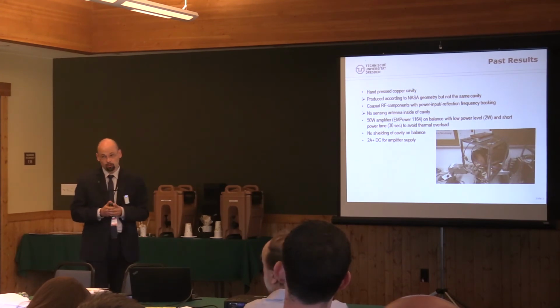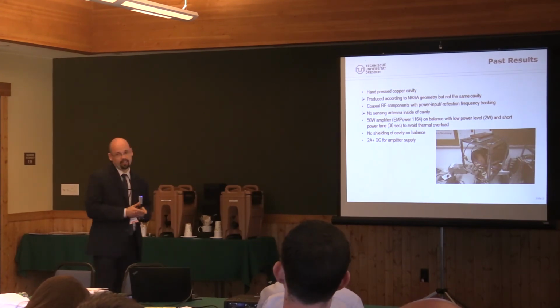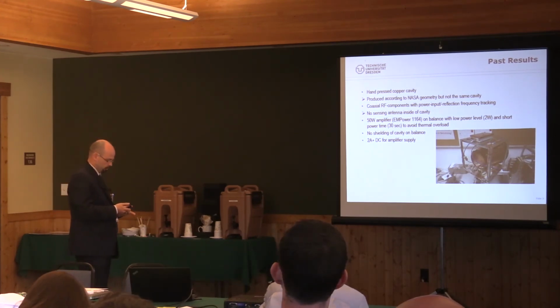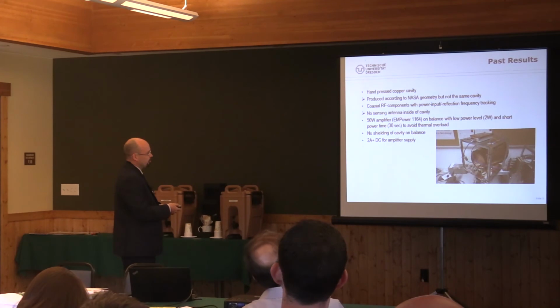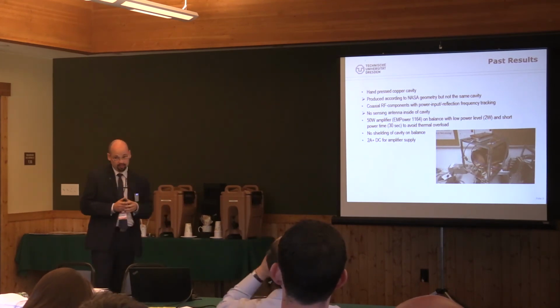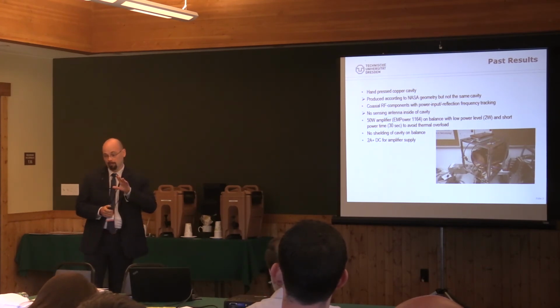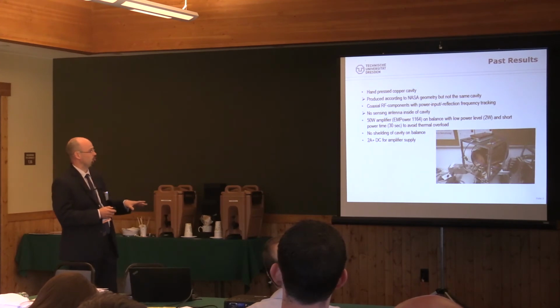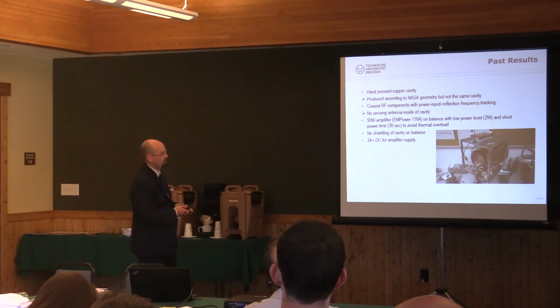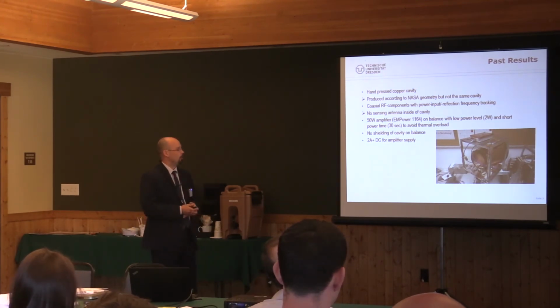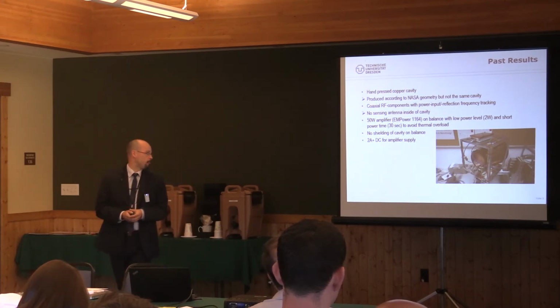We did not use a sensing antenna inside of the cavity in this configuration. We used the already mentioned 50 watts amplifier over the cavity itself, and this was also placed inside the vacuum chamber. So we had massive thermal issues. We were just able to power our amplifier with about 2 watts in a very short time to avoid thermal overheating.